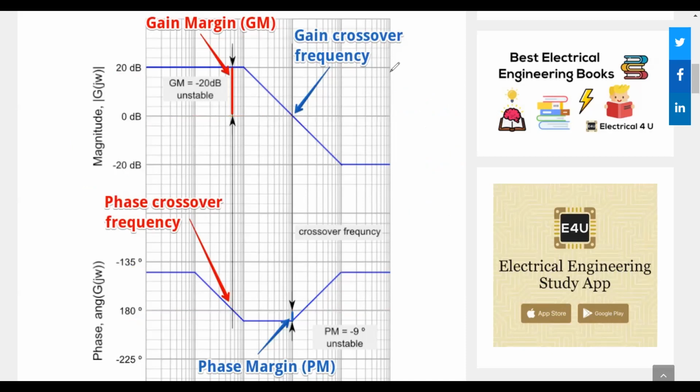the key concept in Bode plot analysis is margins, stability margins. What are stability margins? Well, let's look again at those 2 danger points. What we can see is this plot can go down by 20 decibels, right?